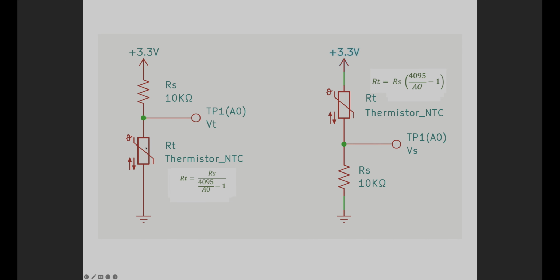We're going from our 25 degree standard range down in temperature. So when the temperature starts to decrease, the resistance of the thermistor increases, which will give us a higher voltage at VT. So we have voltage increasing as our temperature measurement range goes from 25 down. As opposed to here on the other side, where we're measuring temperatures from 25 degrees, our standard base, up toward 100. As the temperature goes up, the resistance decreases, so we'll start to get a higher voltage across our 10K resistor.